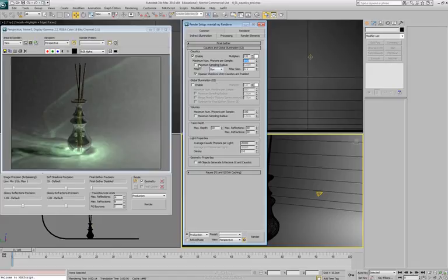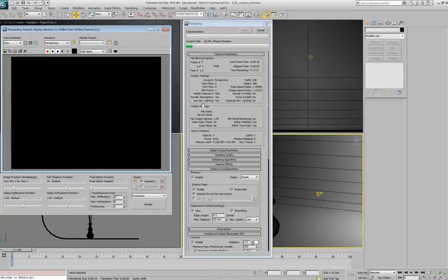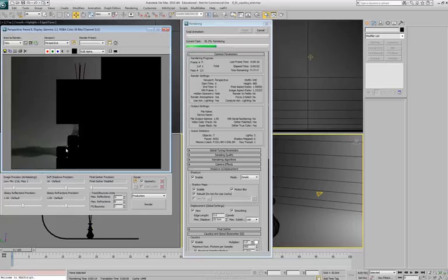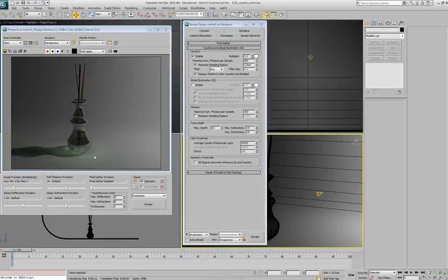Now below that, we've got our maximum sampling radius, just like below. Same basic procedure. We can turn this one on. By turning it on, we're simply sampling a greater distance around and smoothing out between that. So let's say we leave it at the 1.0 and then re-render this. Now what's basically going to happen is it's going to smooth out our caustic effect. And you can see it smoothed it out too much. We're almost just so blurry that we're not getting any of those nice little clean lines that you expect in a caustic to come through.